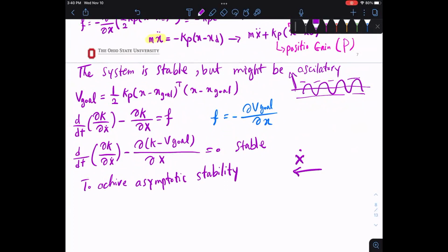When the prismatic joint is moving, it has a velocity, right? How do you stop something from moving? What has to be 0? The velocity, right? The position changes, but once your velocity is 0, it means that you stop. So if I have a velocity vector, because I'm trying to define something that makes sure that my system stops where it's supposed to, I can artificially create a force that opposes the velocity.